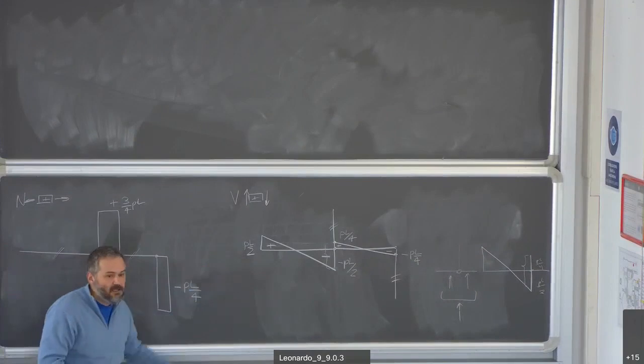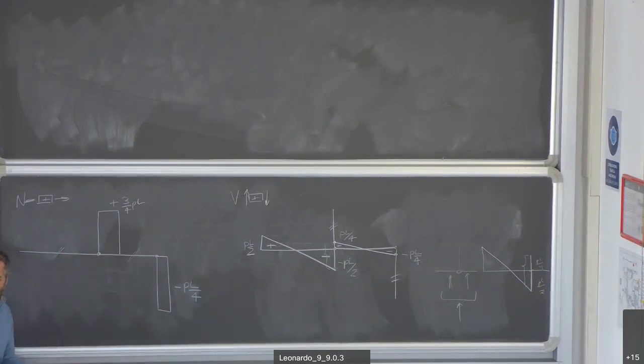The same here. So, answer simple and straight. When you plot internal forces diagrams, draw all the members, even if they are subjected to an internal force which is 0.